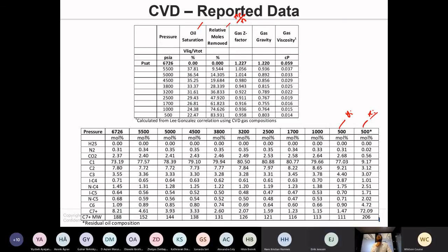But again, PVT labs doing this simulation with an equation of state model is also sometimes dangerous, because if they have measurements and they see that the equation of state model is predicting very different results, they can just try to correct the results with an equation of state model to make it look more realistic. And then, if the end objective of the PVT data is that you try to tune an equation of state model, you will be more happy with the results, because then they will be falling very closely with your EOS models.